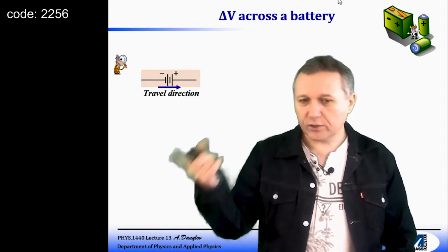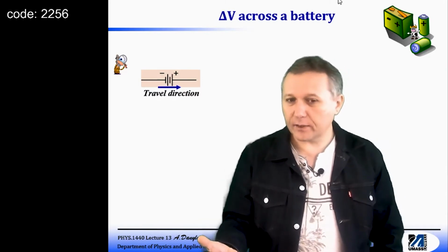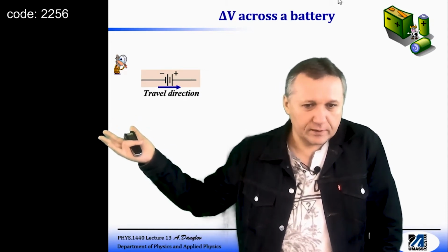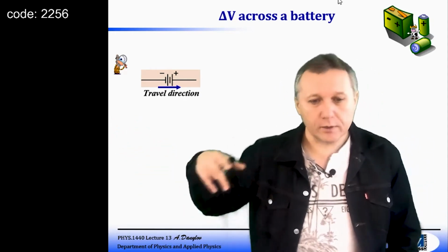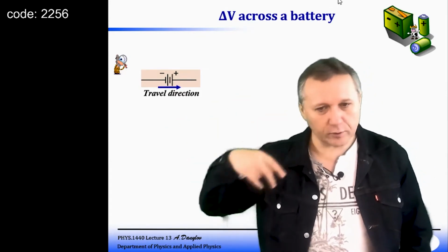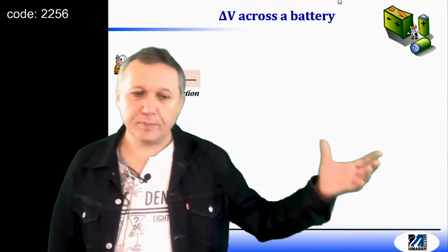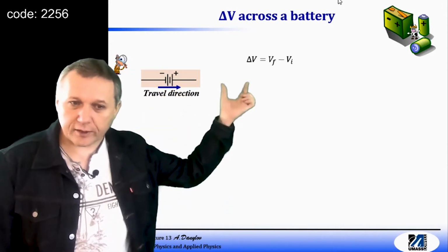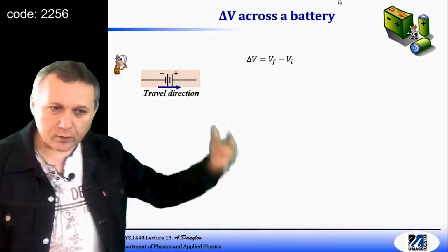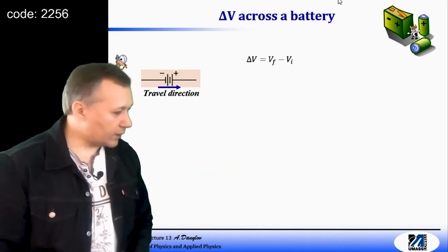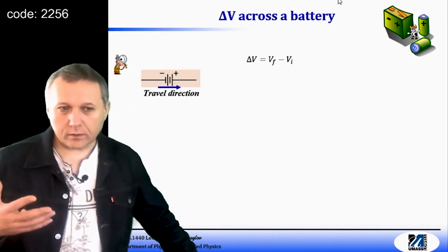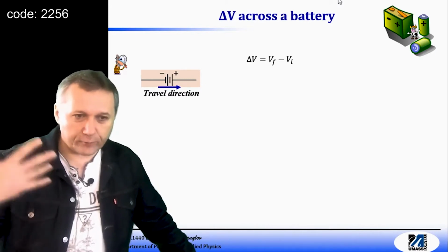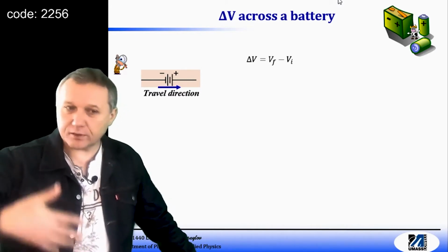It's basically just changing a direction. It's like multiplying the whole equation by -1. The equation will be basically the same. So don't think, just pick a certain direction, clockwise or counterclockwise, and follow it. Okay, so let's assume we pick this direction. And now, of course, what are we trying to calculate? We're trying to calculate delta V. And now I can justify why we need a travel direction. What's the logic? Why am I forcing you to pick this travel direction all the time?